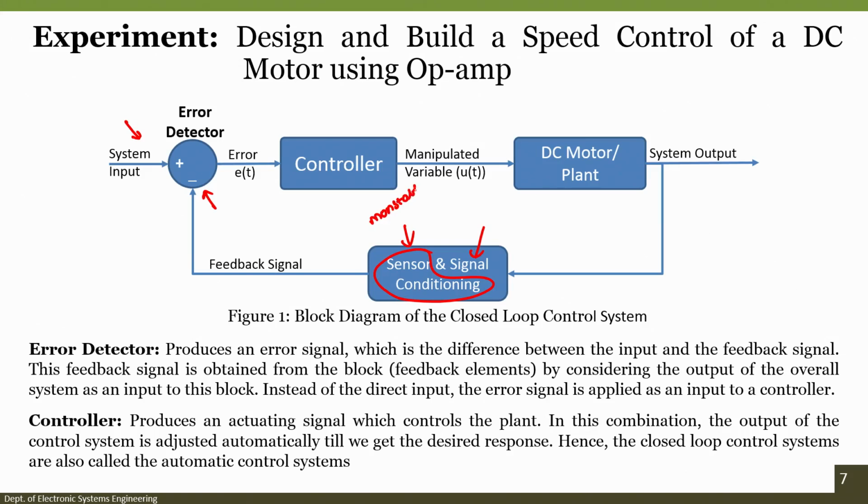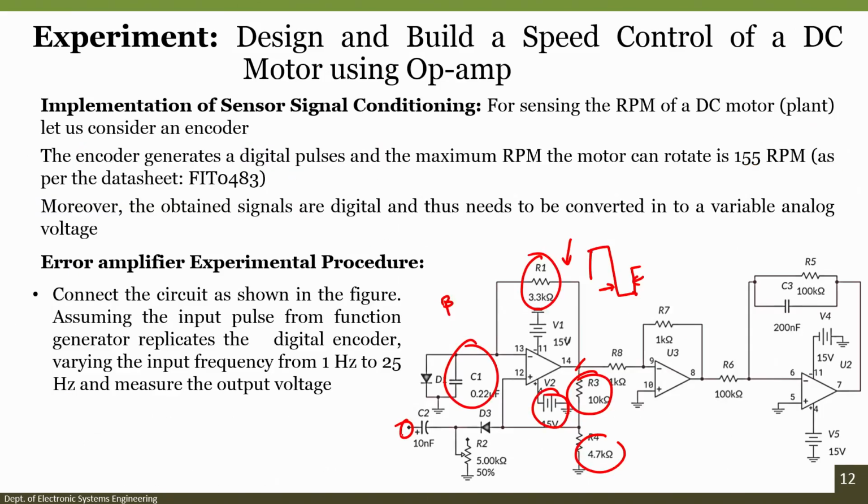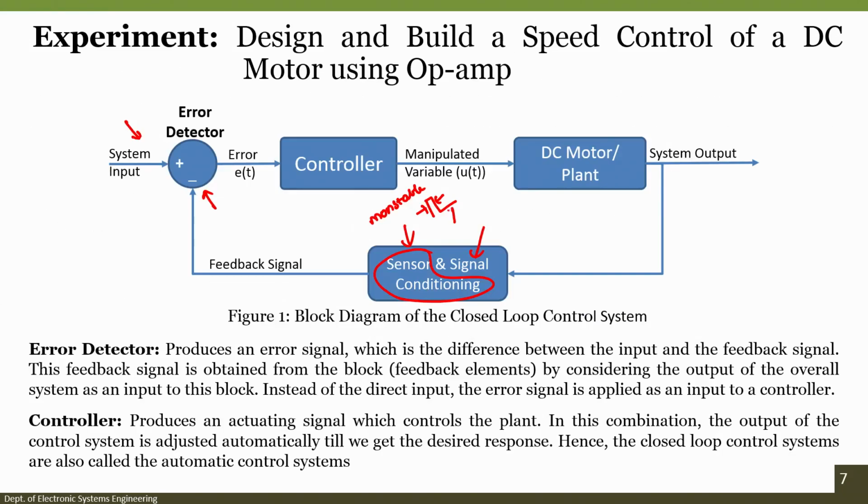So, after the monostable multivibrator we got a fixed time duration of a pulse, either the on time pulse or the off time pulse, one particular pulse is always fixed. And we have also seen that the output of the encoder, which provides the triggering input to the monostable multivibrator, should always be from 0 to minus 5 volts, right. So, the next part of signal conditioning is that this pulse has to be converted to output voltage,